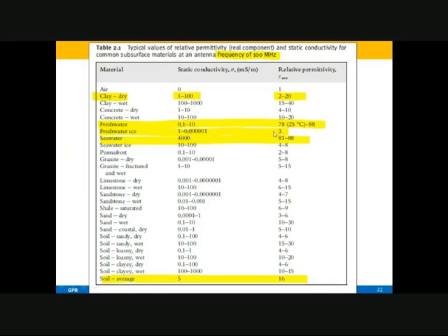The permittivity, the dielectric constant, is almost the same, but you can see the contrast from the conductivity, and when there is a contrast, GPR can work fine. For coastal soil, we generally take the relative permittivity around 10, and for coastal dry soil, the conductivity is around 0.01 to 1. So these are very resistive. The same goes with sand.